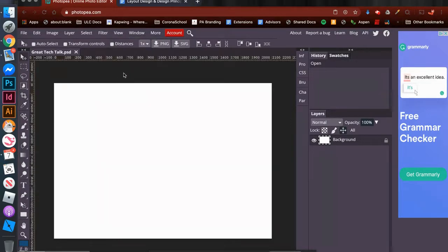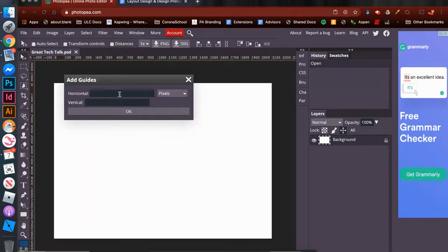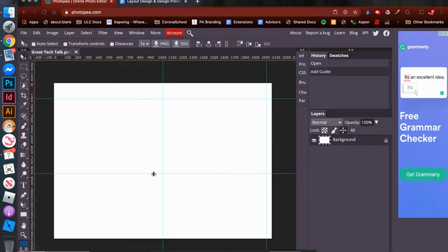Okay. So we've got the rulers, but we want to set up some guides. And these guides are going to help you figure out where to put things on your screen, because you can watch a video, but it's kind of tricky. So where it says horizontal, we want to type in 152, comma 871. Then go to vertical, and it's 1050, comma 2047, and hit OK. You'll see those guides. Hopefully they look just like mine. Okay, there's 2 on the right. One separates the entire thing there.